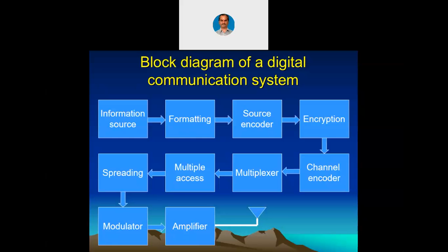Now because of CDMA only, we have 3G and 4G, and in future we will have 5G. All are based on CDMA technology itself. Otherwise, earlier in 0G and 1G we had FDMA, and in 2G, in GSM, we had TDMA. Now TDMA is also there along with FDMA. On top of that there is CDMA, which is a much more complicated spectrum now. That means all three multiple access methodologies can be combined together to have a higher level of data transmission.